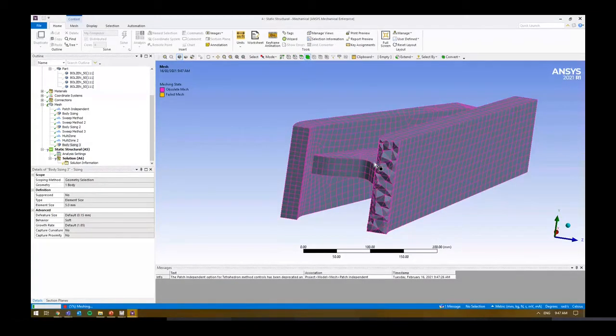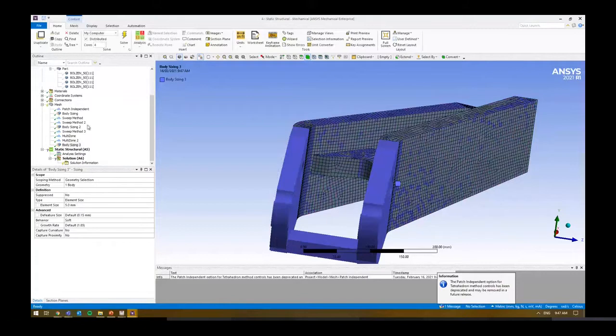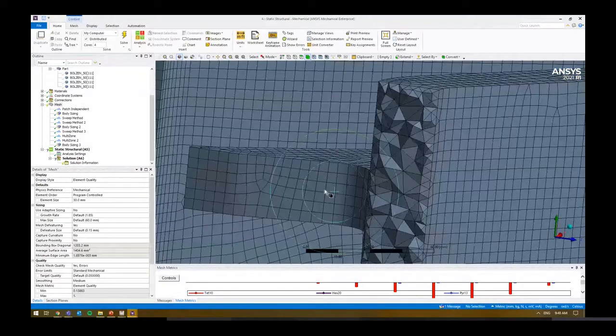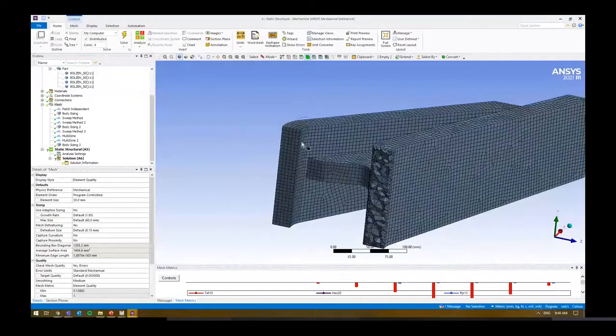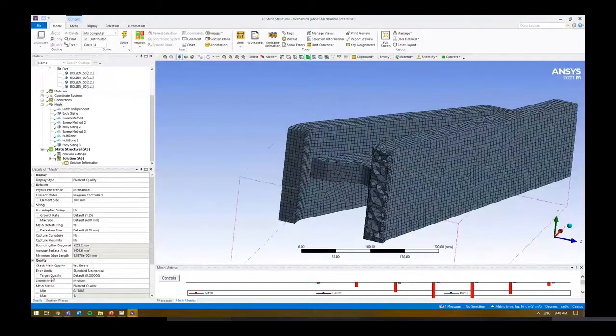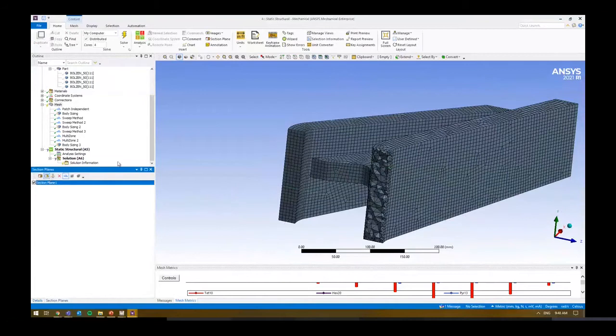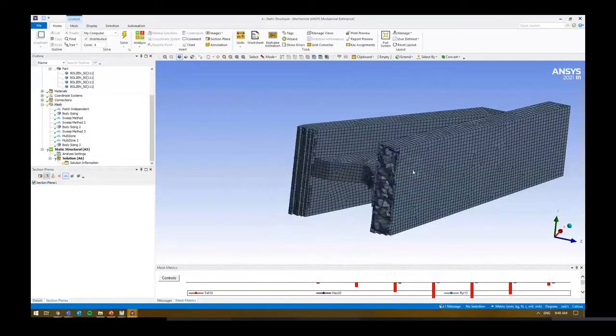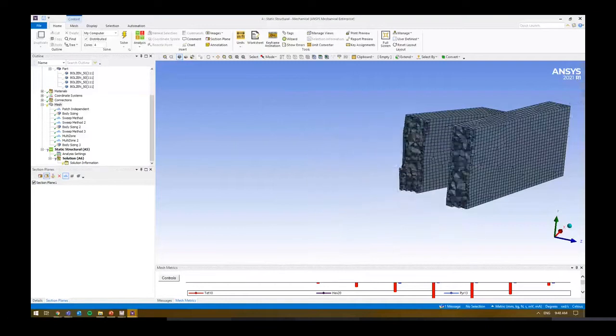If there's no stress concentrations, not much is really happening at this particular component, you don't have to spend a lot of time generating a really good grid on this, right? So it can come down to understanding what is appropriate, what you want to create. Again, you can see here it's able to create a nice grid where we've got the rounds, but around some of these regions it's still having some problems. Well, it's unable to put some hex elements in there, right? And again, you can take a sweep through there, similar through there as well.